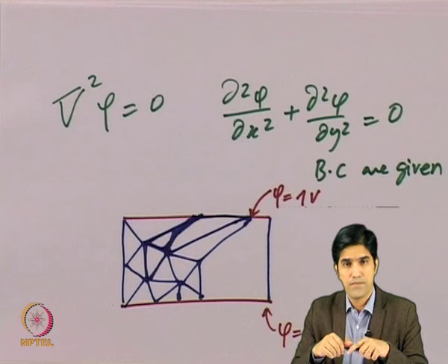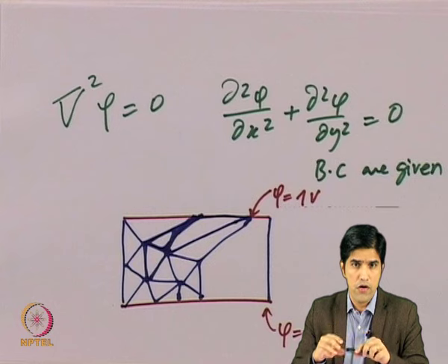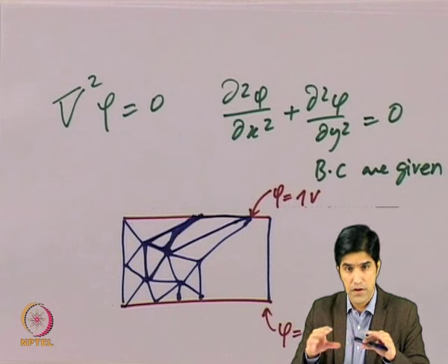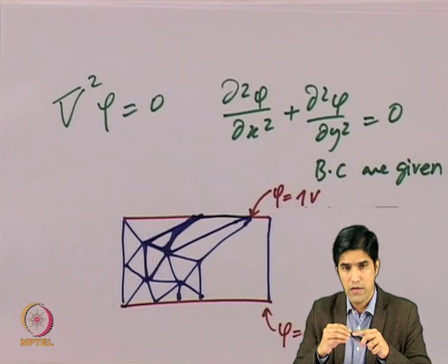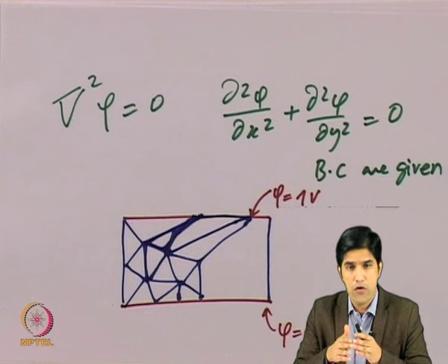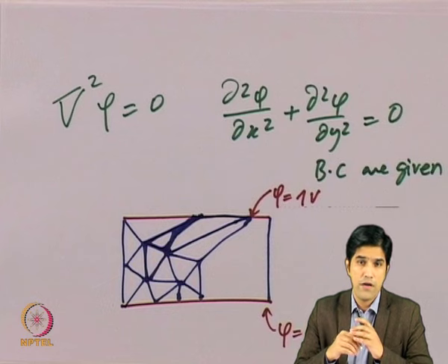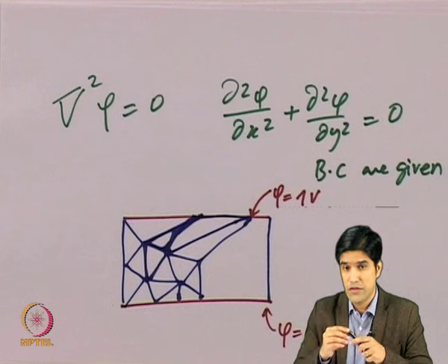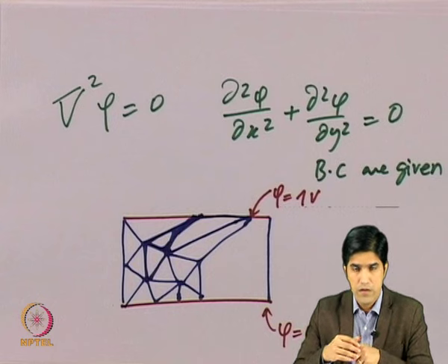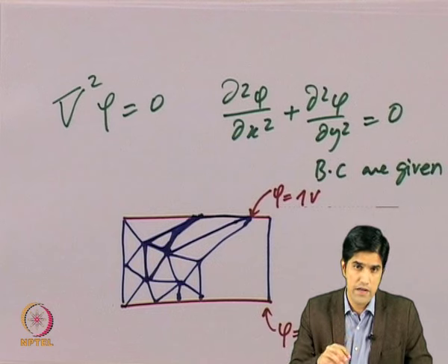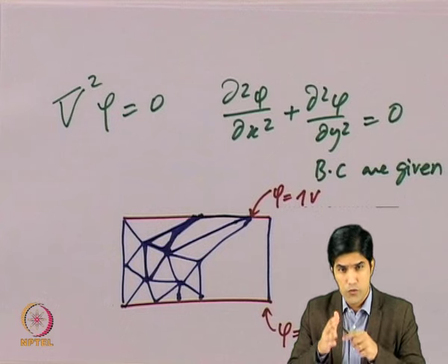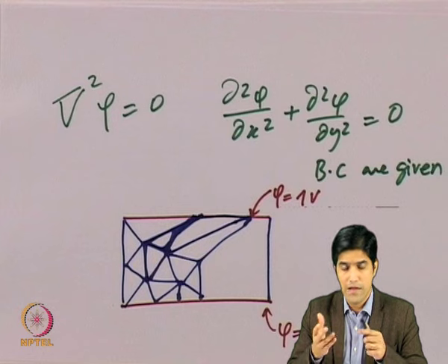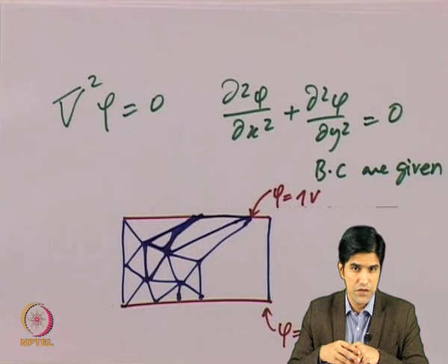But what I am trying to say is, if your program is able to run on any general grid, for example any general triangular grid that does not need to be uniform or regular, that is a good way to start programming. If your program depends on the regularity or uniformity of the grid, then you are very specific and you are not able to solve it using a generalized mesh that can come out of any mesh generator. When I say generalized mesh, I am pointing to a generalized triangular grid. So once I know the shape of the grid, I should be able to run it, without putting so much emphasis on the quality of the grid itself, because sometimes you cannot control the quality of the meshing, and this is mostly the case if you are using a freely available tool.